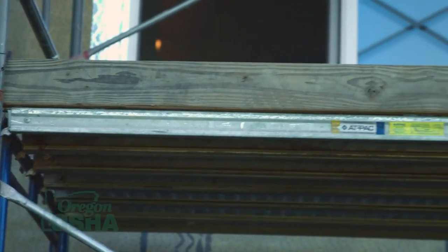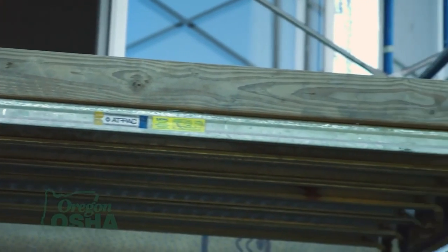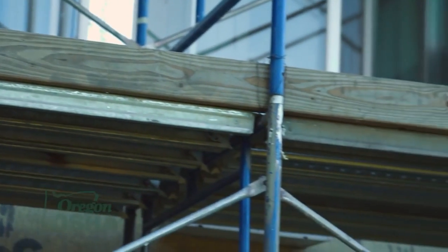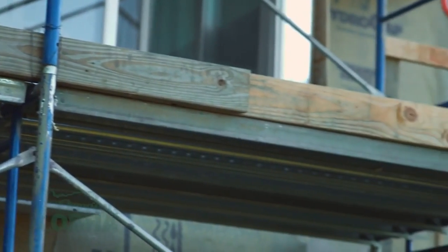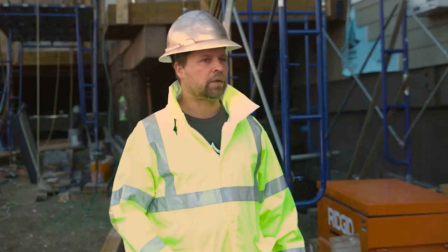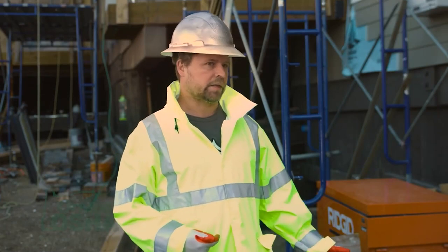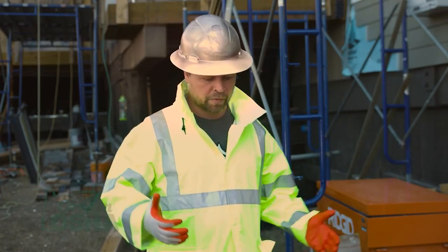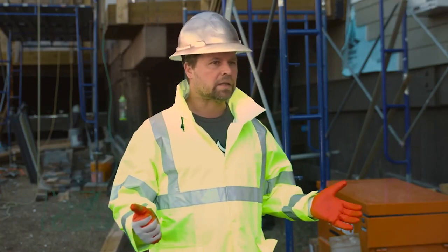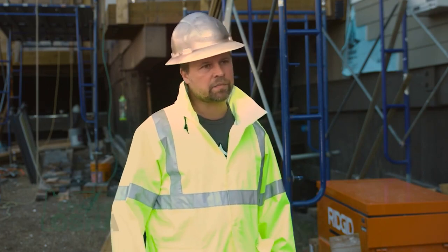Things can fall off the scaffolding very, very easily. Maybe somebody is passing by, so you want to make sure there are some guards against that. You also want to maintain your scaffolding and clean it up. You don't put things close to the edge. You don't put things there that don't necessarily have to be there, since there are other areas for that. Whatever stuff you bring, you want to make sure it's not going to disturb the balance of it. It's common sense, obviously, and good training. Constantly being aware of it is the proper way.